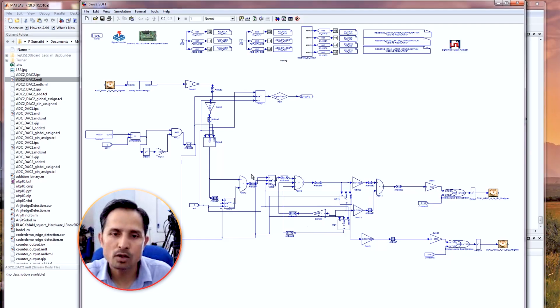So this is the comb part, this is the resonator part, and then after we are converting this signal into the in phase and quadrature phase basically. So this part is used for in phase, and this part is used for quadrature phase. And then we are using two DAC blocks to display this signal to the DSO basically. So these are like 8192 samples.